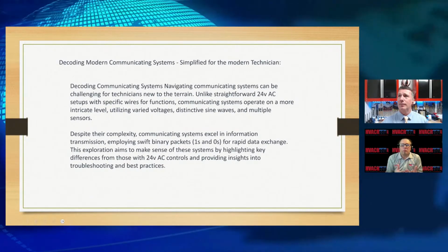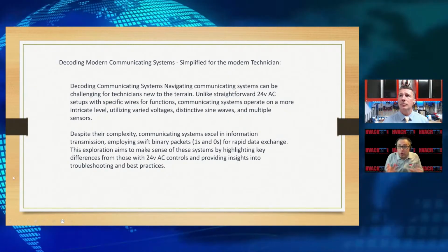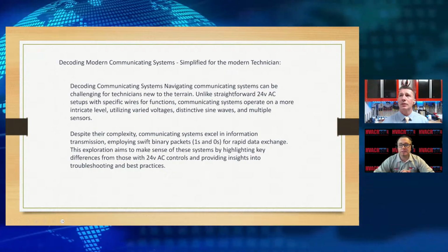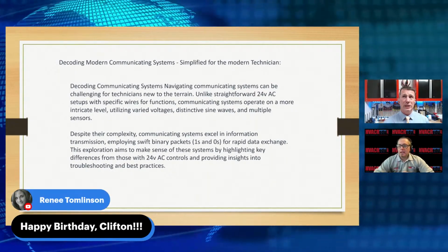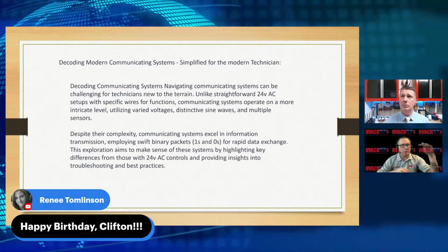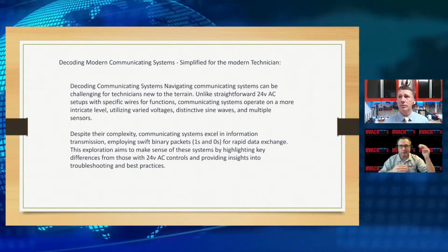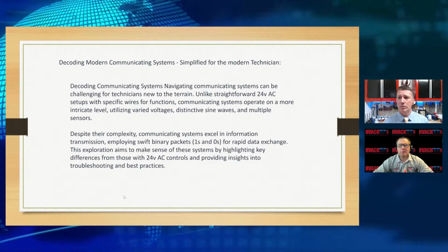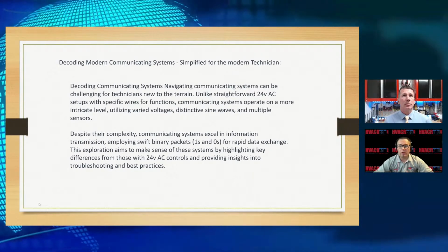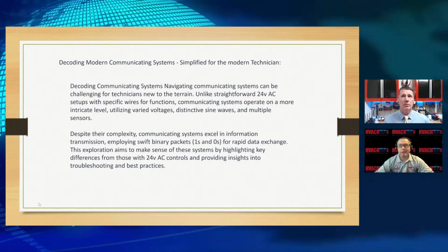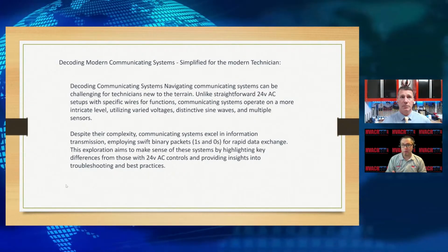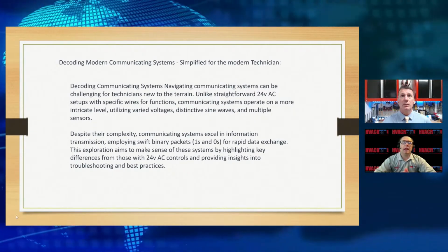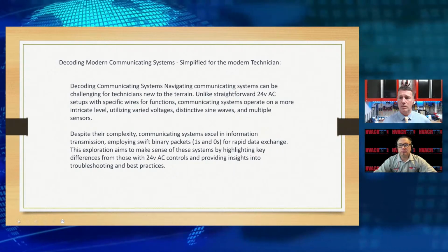Yeah, so most of us, at least in the residential or unitary type split systems, are accustomed to 24 volt, like a switch, and usually that's done. So I'm going to kind of combine this slide and next slide, I believe they overlap here. In a 24 volt system, we have a thermostat. In a communicating system, it's no longer a thermostat; it's now a network controller.